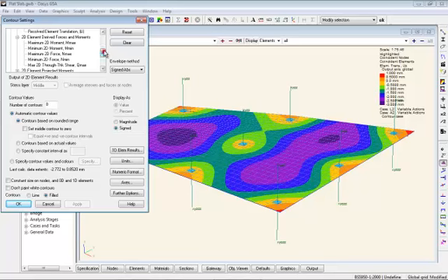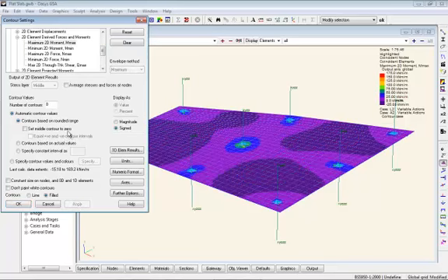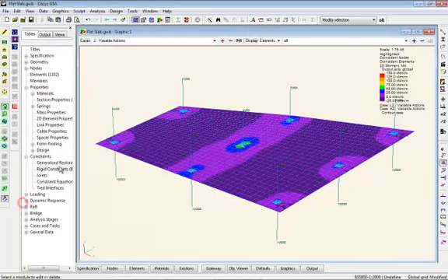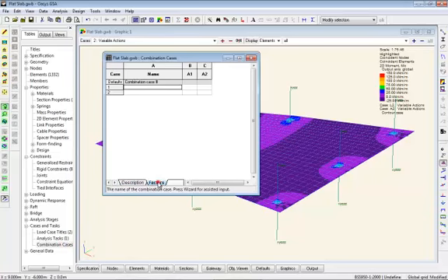We also have maximum, minimum moments, and so on. But we're only interested in projected moments. Now, this is a projected moment for just the live load, but I want an ultimate limit state case. So, as it's linear analysis, I'm going to do a combination case of the dead and the live loads.